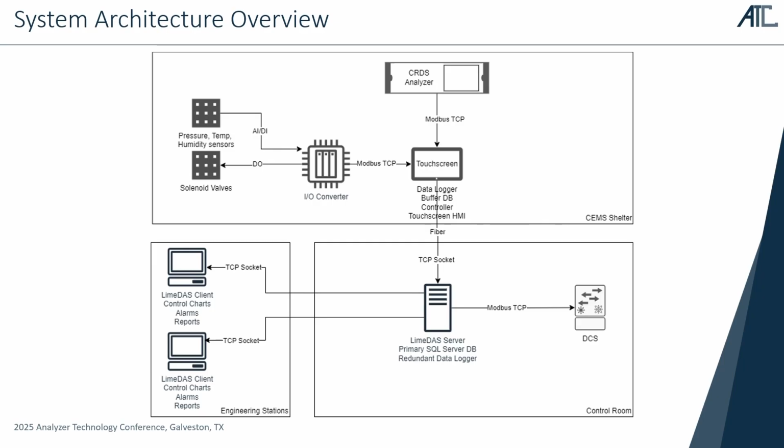And then for the outputs, we use the same converter, a PLC or just a simple I/O module that would send the data from the digital commands to digital outputs to energize various solenoid valves. And that's very important when it comes to controlling the multi-sampler that we're going to be talking about.